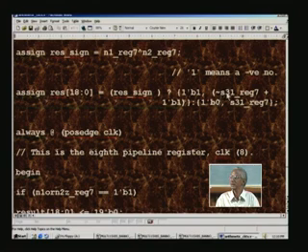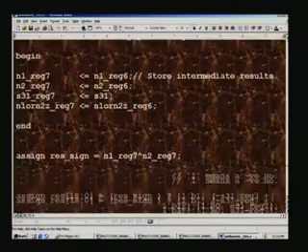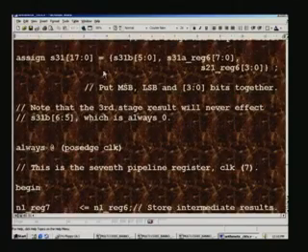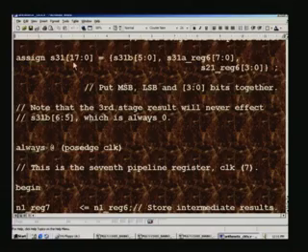I said incorrectly earlier, the sign bit will have to be dealt with separately, and so here what we had to do is just take the 2's complement of S31. S31 is the actual result here in magnitude form, the entire result 17 through 0.